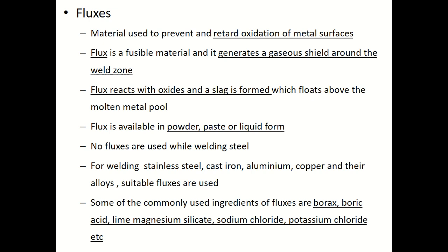Please note that no fluxes are used while welding steel. For welding stainless steel, cast iron, aluminum, copper, and their alloys, suitable fluxes are used. Then what constitutes a flux? Some of the commonly used ingredients of fluxes are borax, boric acid, lime, magnesium silicate, sodium chloride, potassium chloride, etc. A combination of these constituents is generally used as ingredients for the fluxes.